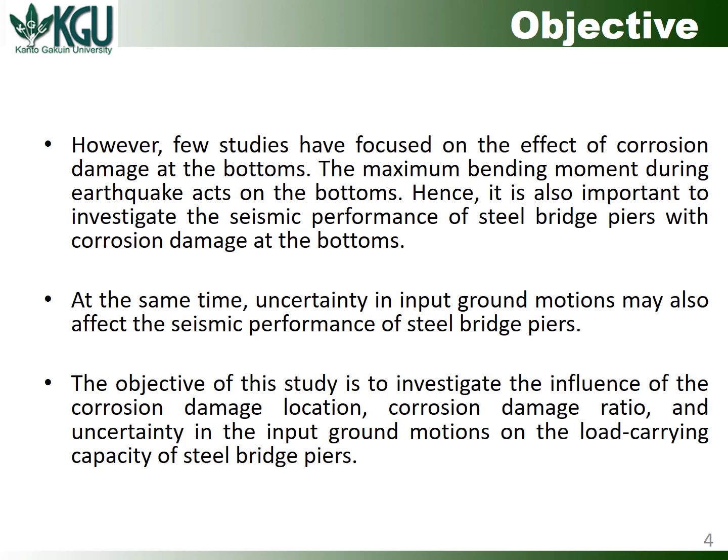At the same time, uncertainty in input ground motions may also affect the seismic performance of steel bridge piers. So, as a consequence, the objective of this study is to investigate the influence of the corrosion damage location, corrosion damage ratio, and uncertainty in the input ground motions on the load carrying capacity of the steel bridge piers.